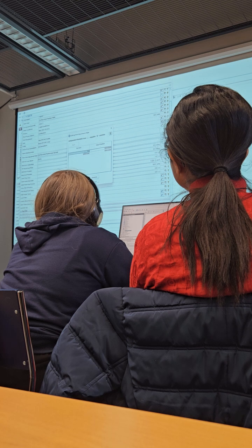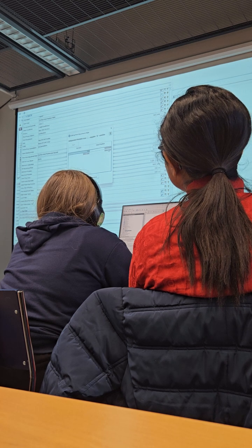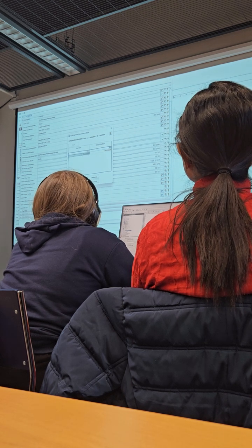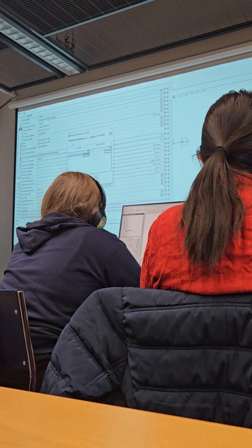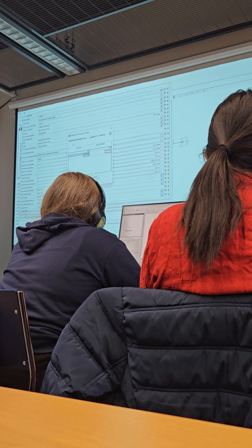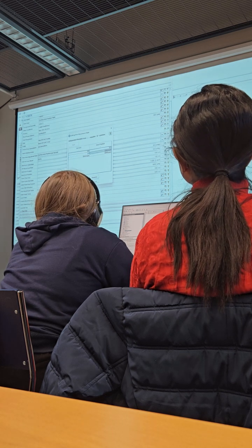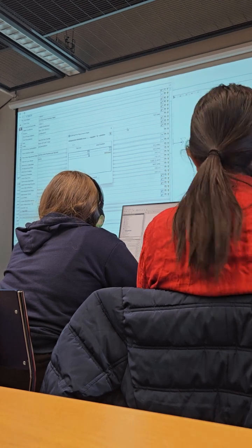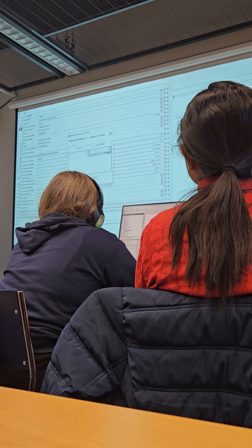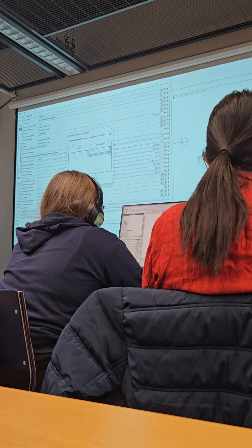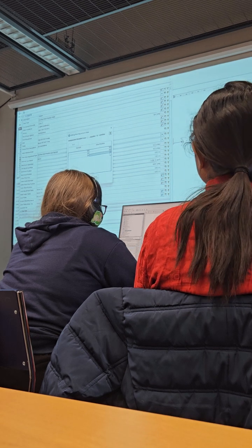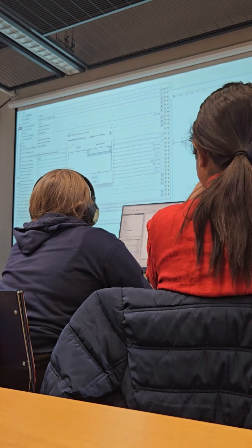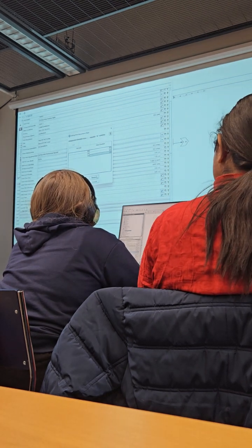So that here it refers that at the time of 0 the area fraction is 0, then it's fully closed, and then we can add more. If I put in 2 seconds it's still closed, but then I can put in time of 3 seconds I put it fully open. So this is a very simple way that I can control the valve opening. And now the rest is it is kept open, so I don't have to close it.